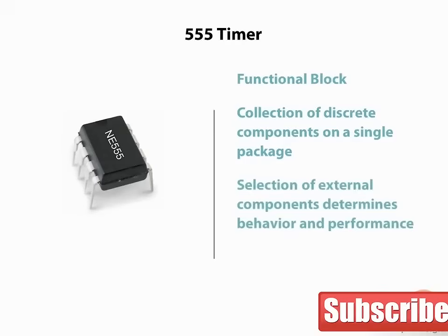The 555 timer is an extremely useful little device, and it can operate in two modes. One is astable and the other is monostable. We're going to wire the 555 in a basic astable configuration and use the output to control the flashing of an LED.